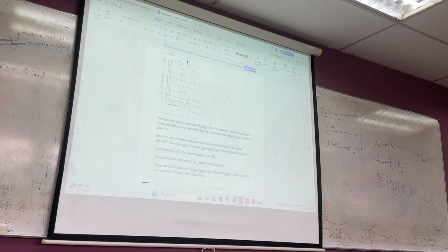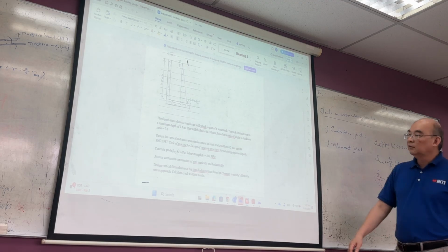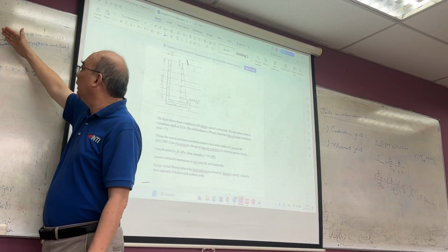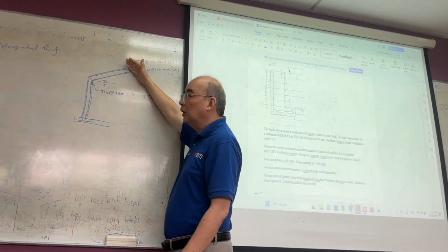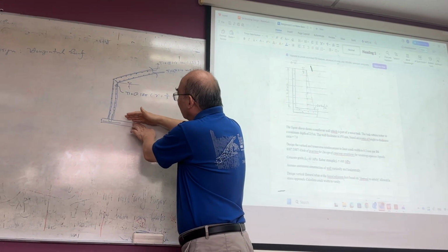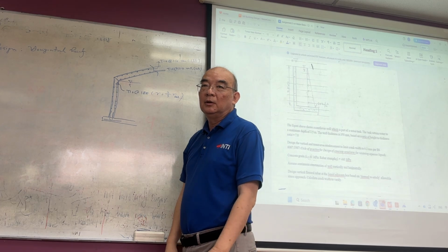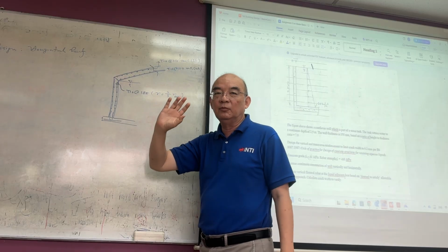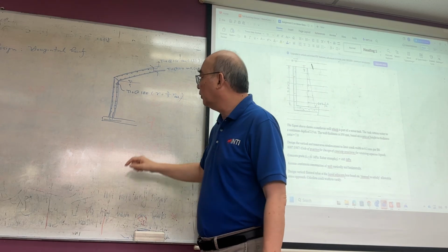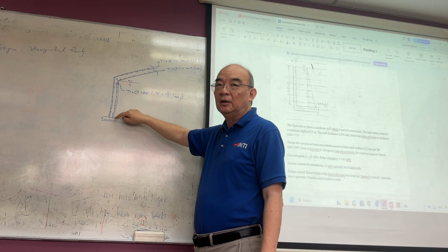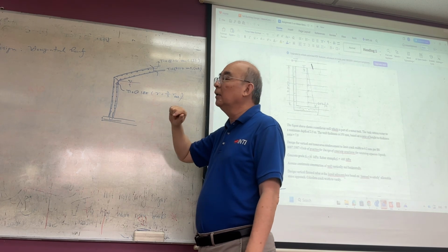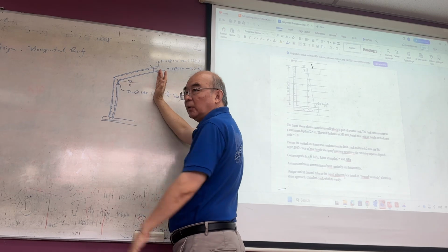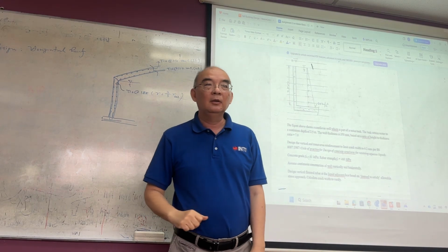Assume continuous construction of the wall vertically and horizontally. Normally vertically will be continuous. In other words, they have the construction joint here, a vertical construction joint, and then they cast from bottom to top. It's not that we don't have horizontal joints; the only horizontal joint is here. If we had horizontal joints, you would cast here and then another one. Normally we don't do that.